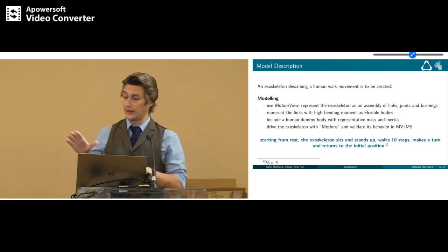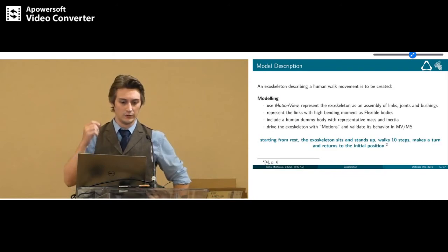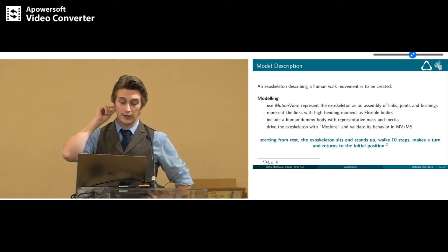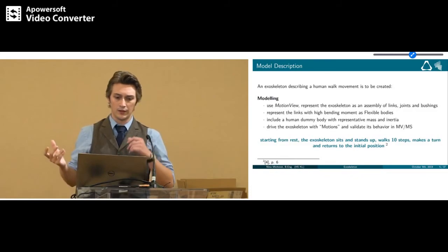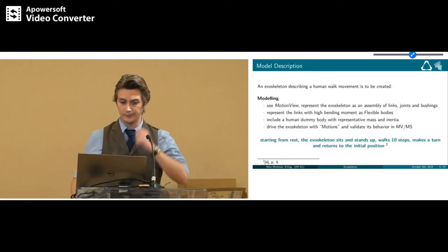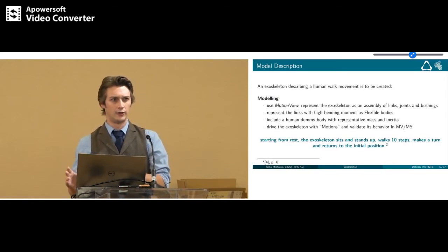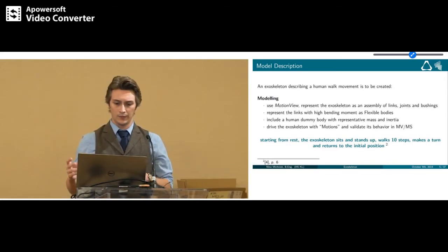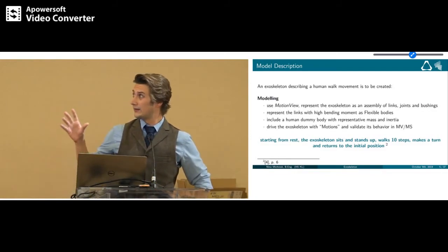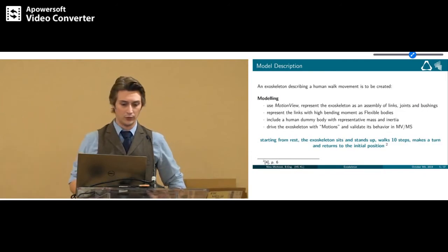And some facts to the modeling. This is an excerpt of the model description. Obviously, I had to use MotionView to represent the exoskeleton. And I had to use flexible bodies that allow stress contours and deformation. And I had to include a human dummy. And in the beginning, I had to drive the exoskeleton with motions and validate its behavior in MotionView, MotionSolve. And there's one sentence of this model description which you can see at the bottom in blue.